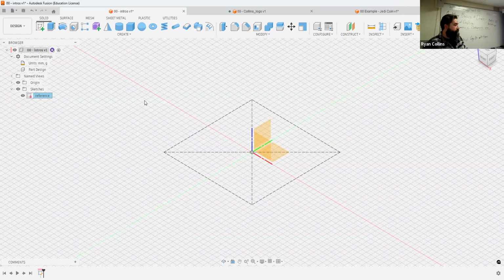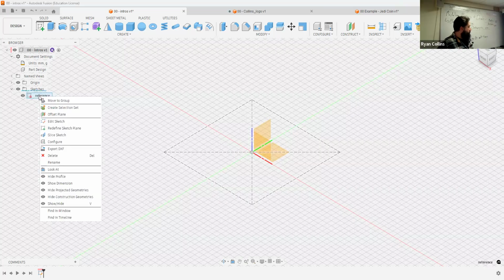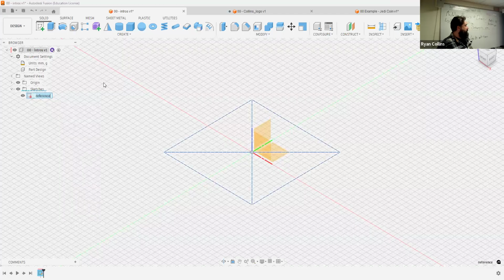Okay, how do I name it? You can just right click on the sketch. Look up here on the tool where we open up the folder that's floating. The origin, the sketches, yep, and just rename. Or if you just slow click on these, it does the same thing. And there you go. So we've started a sketch.